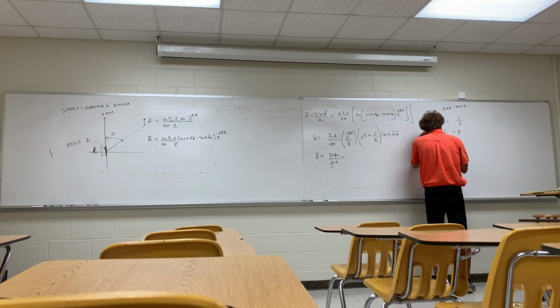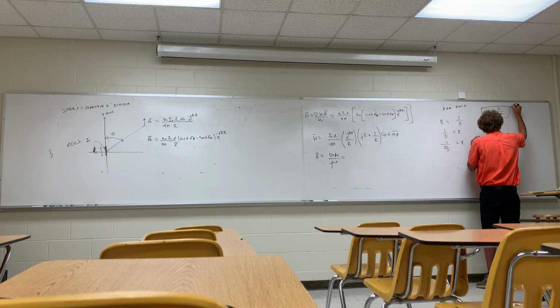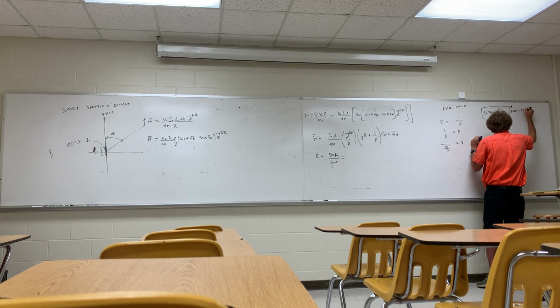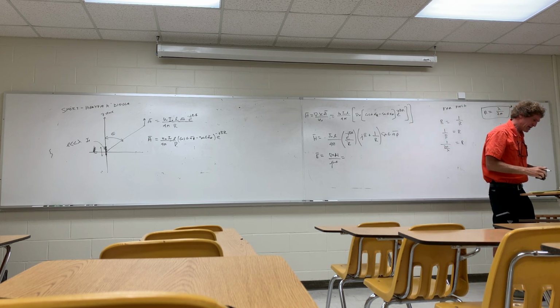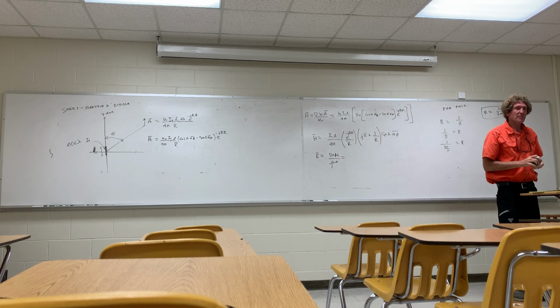And I know beta is 2 pi over lambda. So then I say the point where the far field actually occurs is lambda over 2 pi. And this is the point beyond which you are considered in the far field. And he has that in equation 8.48. Do y'all follow me on that, class?